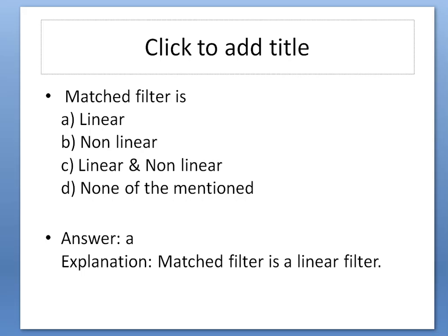We also covered different relations between the receiving power, transmitting power, and lambda with respect to distance. After that we estimated the frequency-dependent path loss with one example, considering one frequency at 30 MHz and another at 60 MHz. We calculated the effective area along with the path loss and made a table. In the table we concluded that as the frequency increases, the path loss is affected proportionally. And finally in the session we discussed thermal noise.